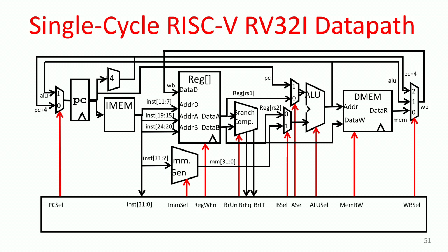And then what remains in the processor design is really worrying about this part down here. Right. Now, the logic down in the controller. That's the part that takes the instruction and the various other signals that come into it and generates all these control signals that go up to control the type of immediate, all the muxes, the write enable signals for the memories, all that kind of stuff that comes from the controller. So it's kind of like a table lookup operation, really. Based on what type of instruction and some other input, you can generate what the control signals should be, right?